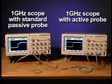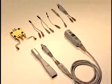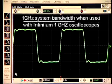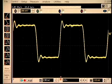The difference in signal fidelity is dramatic between using an ordinary passive probe and using an active probe like Agilent's 1130A Infinimax probe. Active probes, like the Infinimax probing solution, provide two key advantages over passive probes. First, active probes enable you to get full system bandwidth out of your measurement system. Secondly, Agilent active probes come with damped resistive tips to minimize the loading effects created when connecting the probe to the device under test. Without properly damped probing accessories, a probe will load the circuit under test, causing signal ringing and distortion.